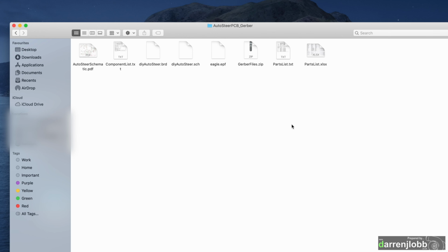If you use a company like DigiKey or whatever, you can actually upload that file to the website and it will generate a list of all the parts you require, all for you, which you can then scroll down through and manually delete bits and pieces that you don't need, because it will order some extra bits that you don't need. And you can also check the stock of the items. There's quite a few items I found were out of stock and with a long lead time.